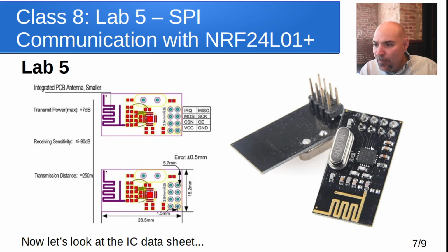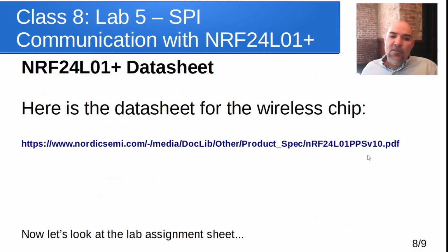The chip itself basically just has an SPI interface. This stuff up here is all capacitors for the RF stuff for communicating with this chip. But for the most part, we're just talking directly to that chip and telling it we want to read its registers. So let's dig into that a little bit further.